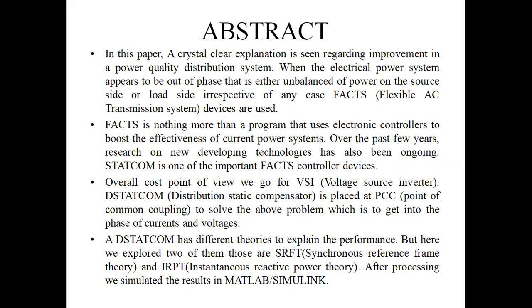STATCOM is one of the most important FACTS controller devices. It is connected in shunt, so it is also called a shunt connected FACTS device. From a cost point of view, we go for VSI, that is, voltage source inverter. DSTATCOM, the distribution static compensator, is placed at PCC, that is, the point of common coupling, to solve the above problem, which is to get the currents and voltages into phase.